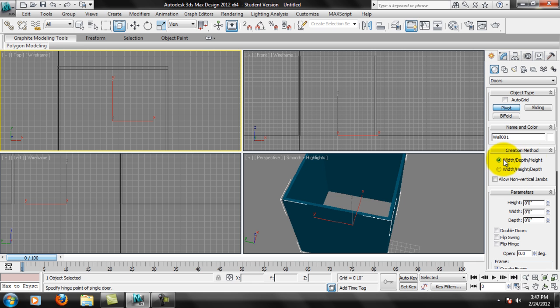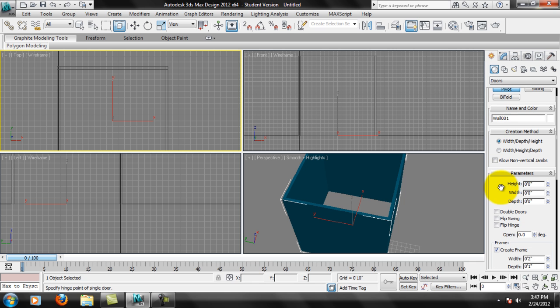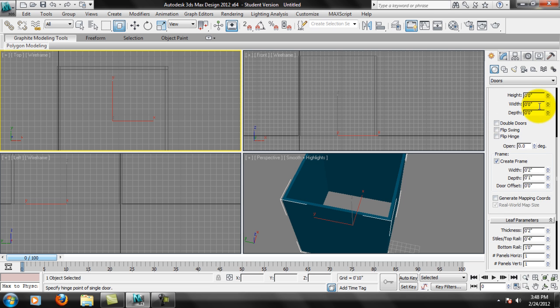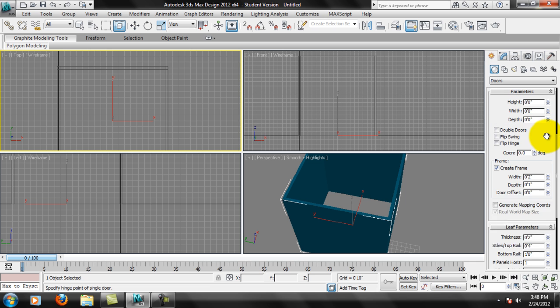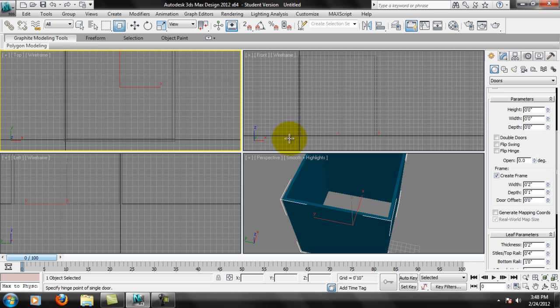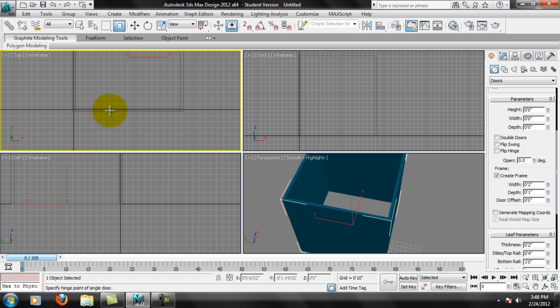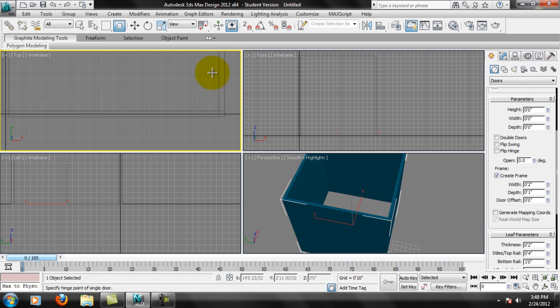I'm going to show you how we do this. It's very tricky. The windows and doors are very touchy, so it's important that you follow these steps exactly. We'll come back and modify these after we actually place the door. The way these AEC components are set up, you have to make sure that you snap perfectly to the inside edge and the outside edge in order for the door to cut through. And what I mean by cut through is, let me go ahead and try to place a door here. I'll place a door in the same order as it suggested.